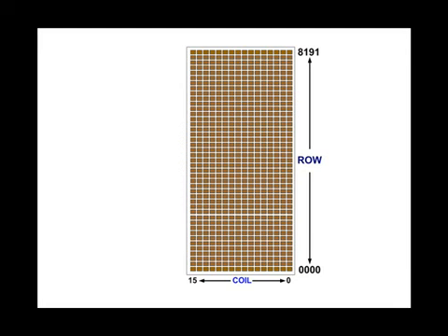You could say that if you want to query or question a particular relay coil to see if it's in the on state, you would use a normally open contact. If you want to query or question a particular coil to see if it's in the off state, you would use a normally closed contact.